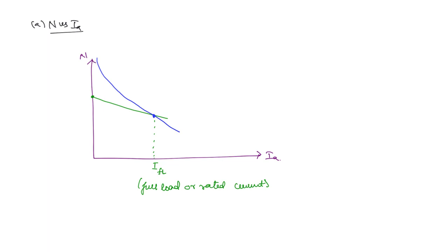And then finally we have the compound motor. So the compound motor will have a specific value, finite value at no load, and then it will keep falling. You can see it is a mix of both the series characteristics and shunt characteristics because it has both the series and the shunt winding. So the characteristics also you are going to get a mix of both of them. You can write here this is shunt motor. This we have drawn cumulative compound motor. So make sure to mention that. It is cumulative motor. And finally the series motor.